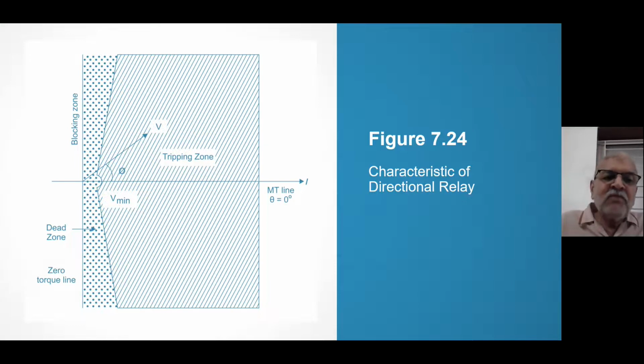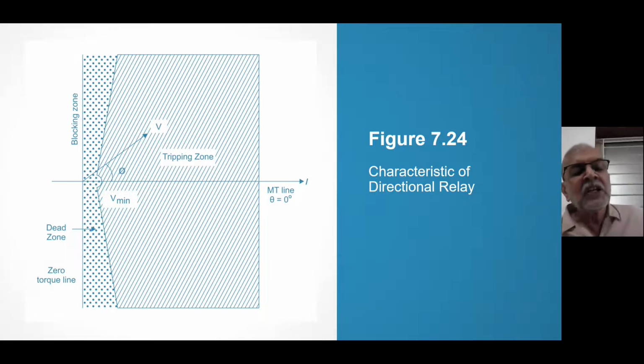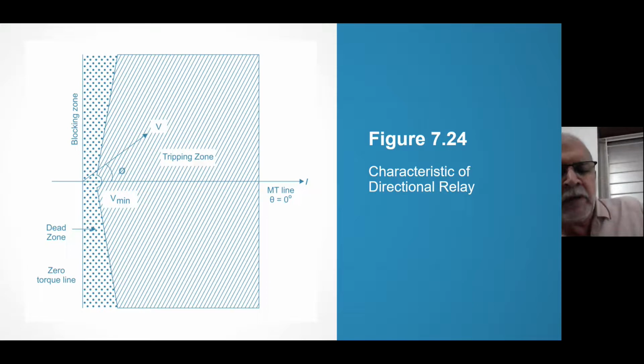But at that time, you see, what was the requirement in an electromagnetic relay? A small cup was rotating, hardly by 1 or 2 millimeters, and the relay was operating based on the cup. It is a simple principle, the same as the induction disk principle used in overcurrent relays. There the distance is more. Here the distance is hardly 2 millimeters, because we do not want time delay.